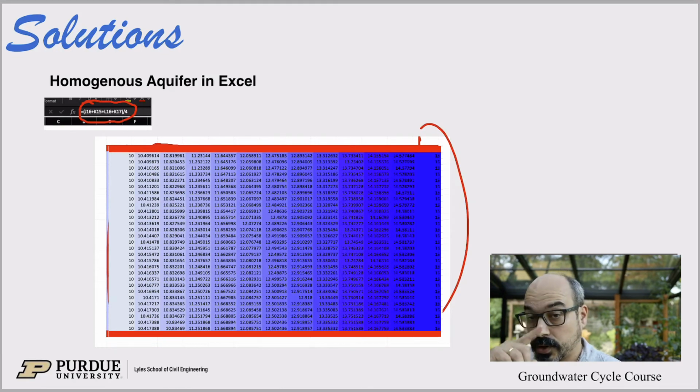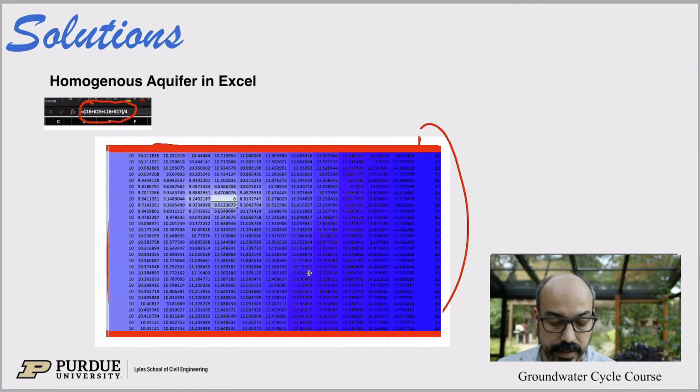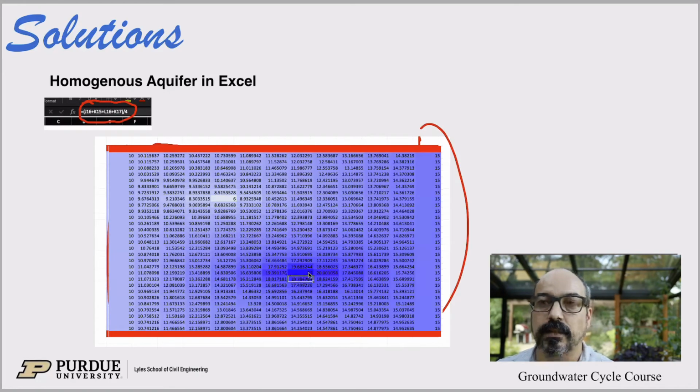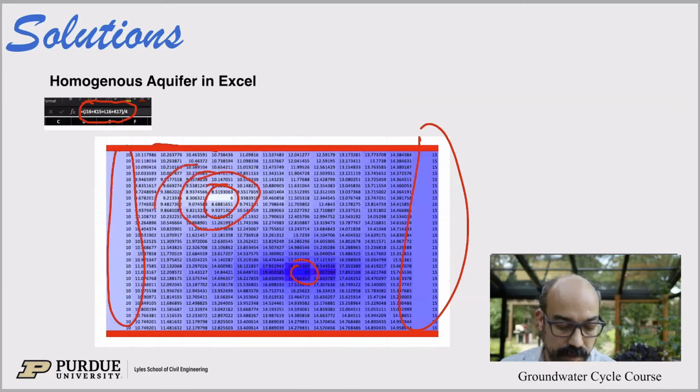Now I play with the code, so here I'm clicking on some cells to add fixed levels. Instead of carrying that finite difference, I'm just saying, okay, this cell is at 6 meters and that cell is at 25 meters here. So these are fixed cells and they're sort of mimicking wells. When we do wells, you can see that sort of halo around. So if we pump down to 6 meters, this is what your piezometric surface would look like.